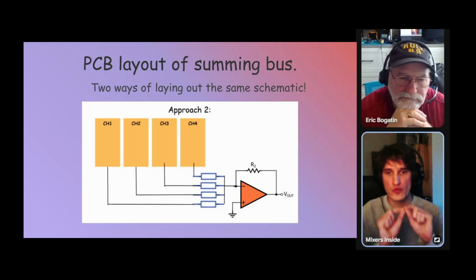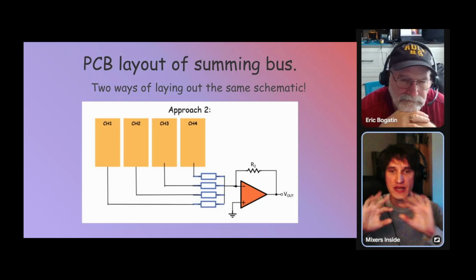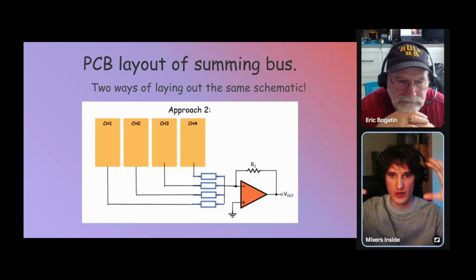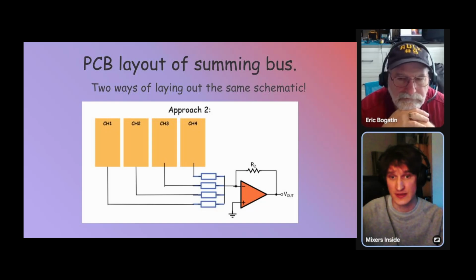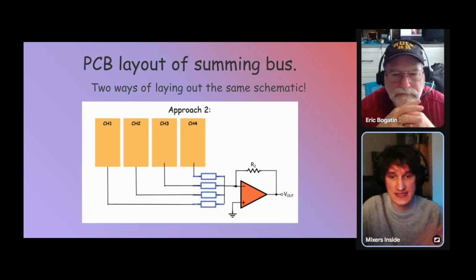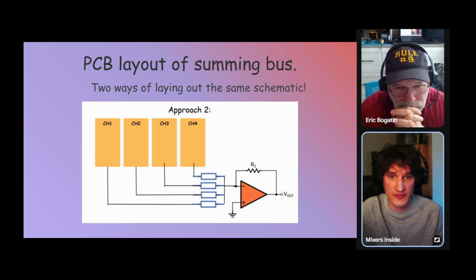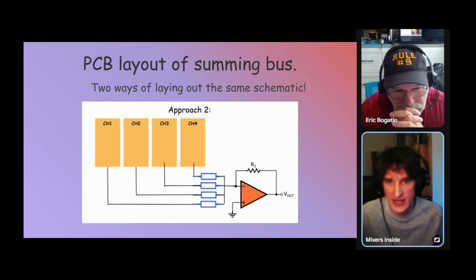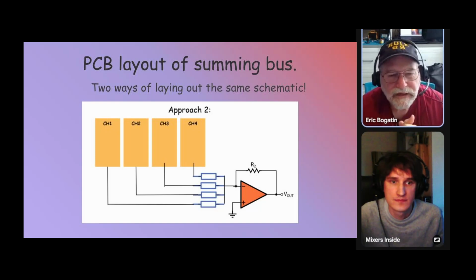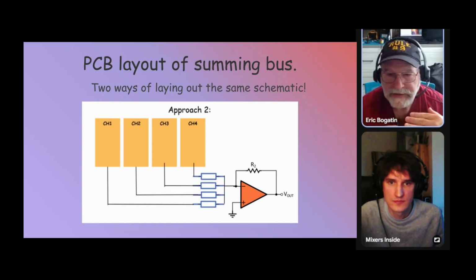And when we make it longer and when we gather the signal from all the boards, the area becomes significantly larger, and it can be more prone to interference. Am I right? So if your traces are controlled impedance, whether you use it for controlled impedance or not, that just means that there's a return plane underneath. We can keep the crosstalk low.